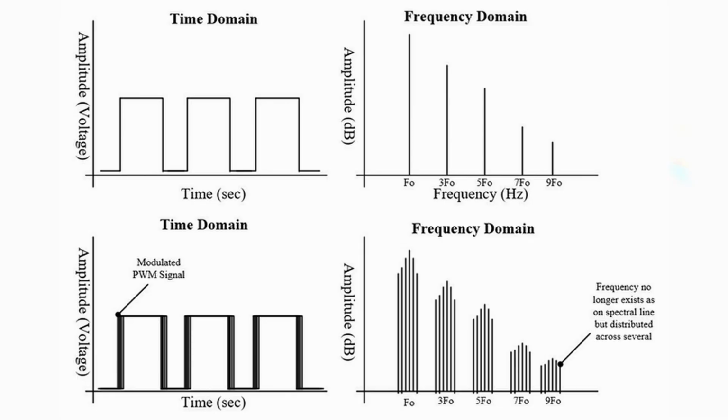The next circuit design technique we have is one of my favorites, and this is a technique known as clock dithering, also known as using a spread spectrum clock. This is a feature that a lot of modern integrated circuits come with, where instead of operating at exactly one single frequency, there is a low frequency oscillator that will slowly adjust the switching frequency of the digital circuit over time. It's enough to significantly impact your radiated emissions, but it's not enough to affect the actual functioning of your device. I really like this technique because it has several advantages.